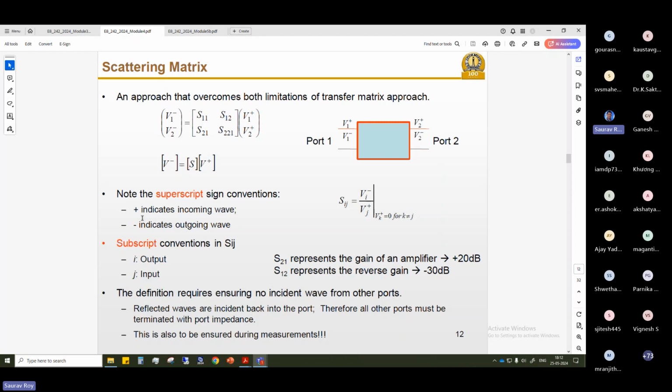So this plus tells us what is the incoming wave and minus is the outgoing or reflected wave. That is why it is vital, because whenever there is a reflected wave, we know that the matching is not very good at that port. If it is highly matched, then the complete wave will go into that port. There will be nothing coming back. So that's why S11 is vital. We want to measure how much incident and reflected power there is. That ratio is the S11.